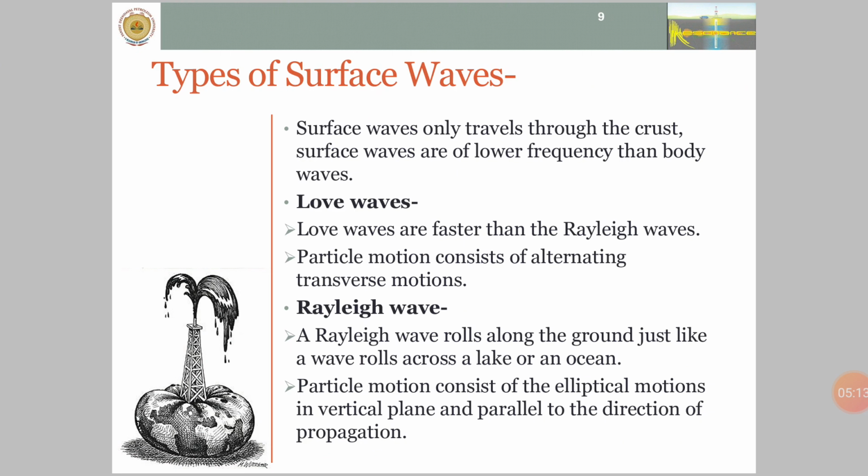We should also understand the surface waves, because surface waves are considered as noise. This has to be removed during the process of refraction. So we should also understand what is the depth to the low velocity layers, because surface waves are low velocity layers, and we have to remove the low velocity layers to bring the datum from the surface to the bottom part of the low velocity layer, which is useful for seismic reflection.